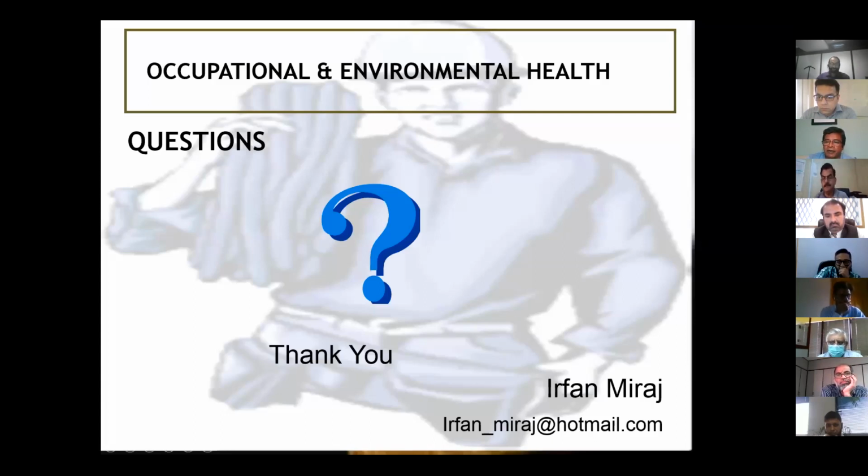Again, for silica, from grinding of concrete, masonry, or mortar on a construction site, at least use wetting techniques. Don't let the fine dust fly all over the place. The mask or protection that workers or bystanders are using is useless. Those particles, if you inhale them, will just cause uneasiness, but the fine particles will cause damage to your lungs. You will be inhaling those and they will not come out of your lungs. The other bigger particles will come out. So proper protection is needed.